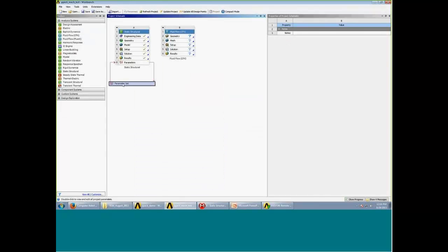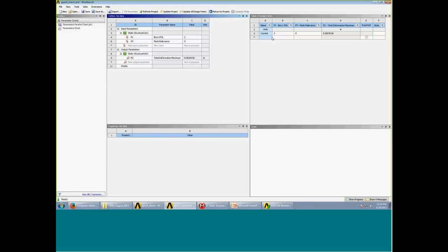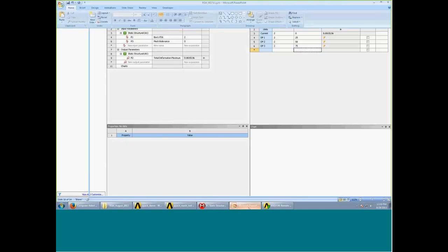And if I come back to the project page and take a look at the parameter set, I can change that relevance and evaluate, okay, if I increase the mesh density, let's say I take a look at 4 different meshes, I can see how the results change based on that mesh parameter.